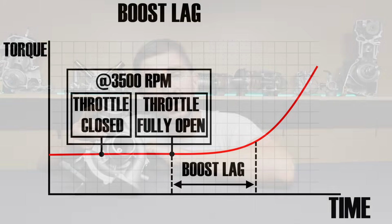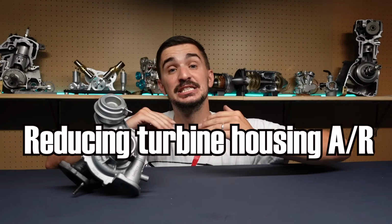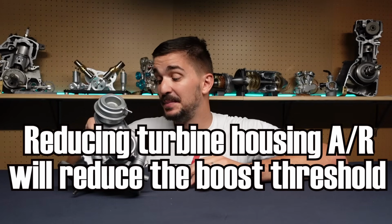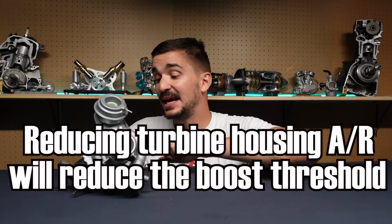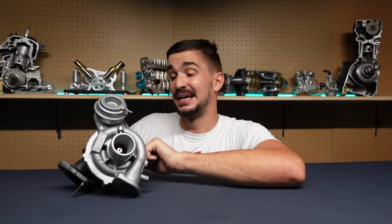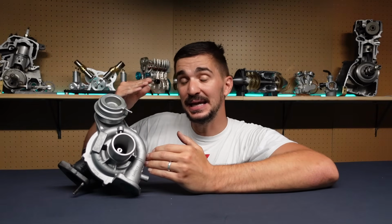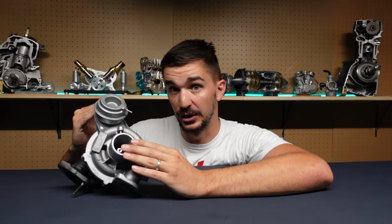Replacing your turbine housing with a turbine housing that has a smaller A over R number is going to reduce your boost threshold. You're going to reach it sooner because it's going to increase your exhaust gas velocity, and that's going to get your turbine wheel and your compressor wheel, because it's connected to the turbine wheel, up to the speed where the compressor wheel can produce significant boost sooner.